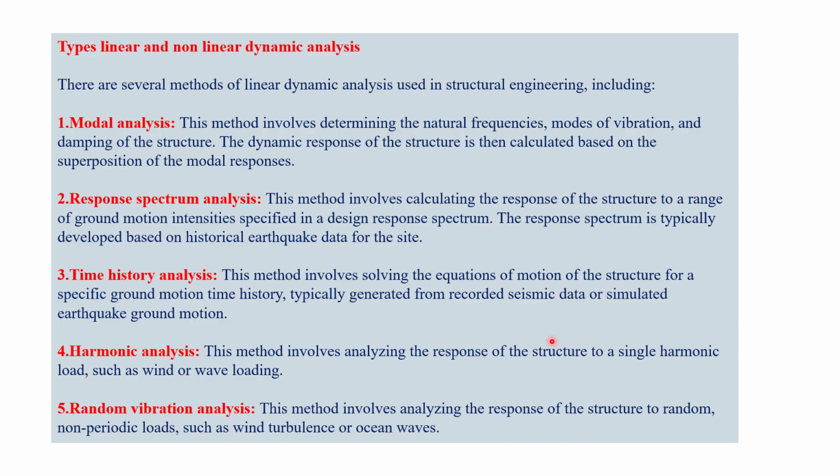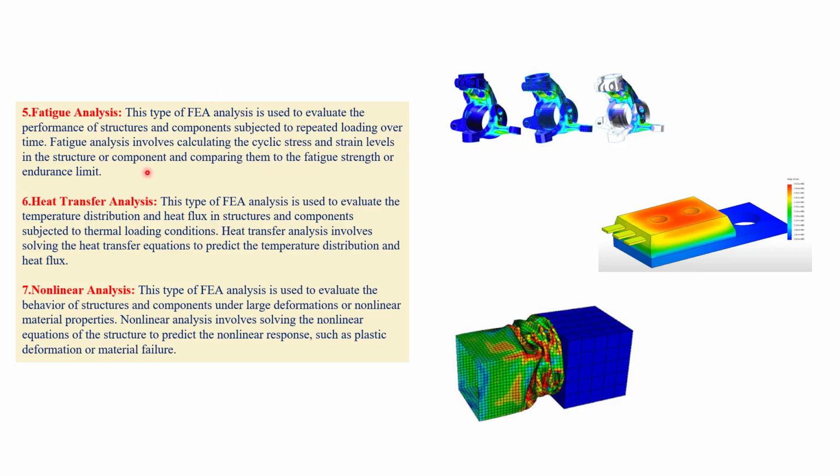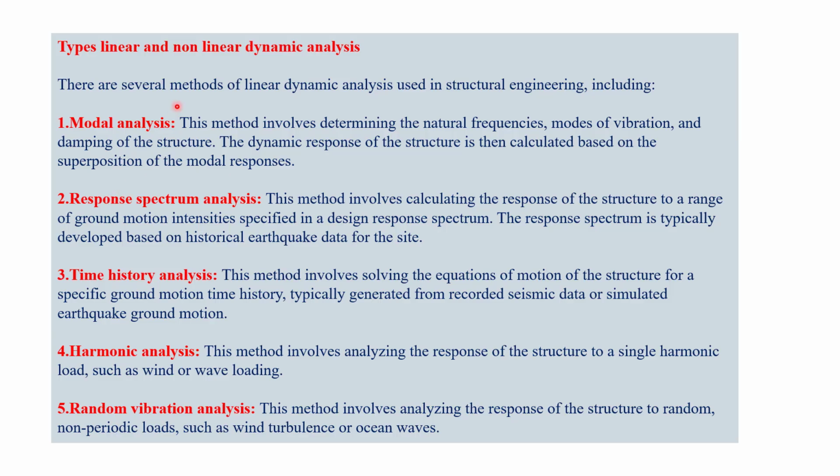Next, again inside the dynamic analysis, if you consider the dynamic analysis, we have again linear and non-linear dynamic analysis. The first one is the modal analysis, where we try to extract the natural frequencies, modes of vibrations, and this is completely linear if you do just a natural frequency analysis. Okay, and then the dynamic responses will be extracted depending upon the modal responses and the superpositions.